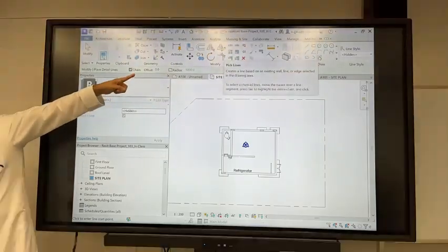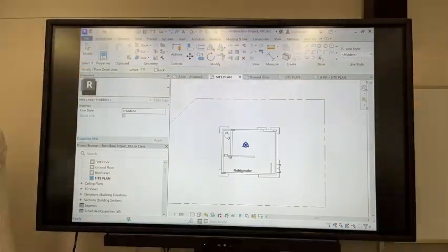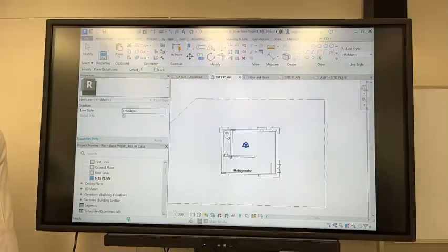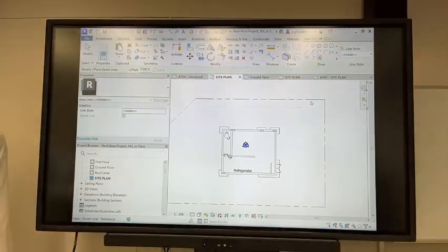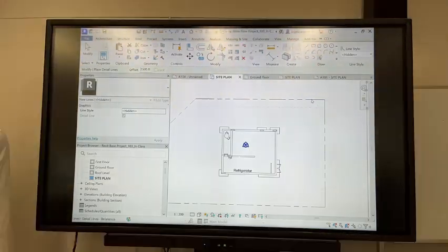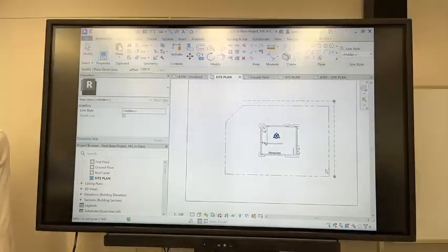It's like a small cursor instead of drawing the lines. You can draw, but yeah, this is a fast way. When you pick the lines, you can do offset. So offset a meter and a half after you figure out that that's a reasonable distance. When you put the cursor, it will ask whether you want the offset to the top or to the bottom. My dimension is on top, so I draw this. I do it here.